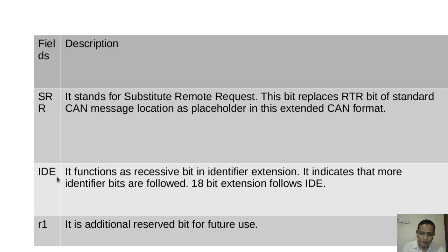Then the IDE functions as a recessive bit in the identifier extension. It indicates that more identifier bits follow, that is, the 18-bit extension follows the IDE.